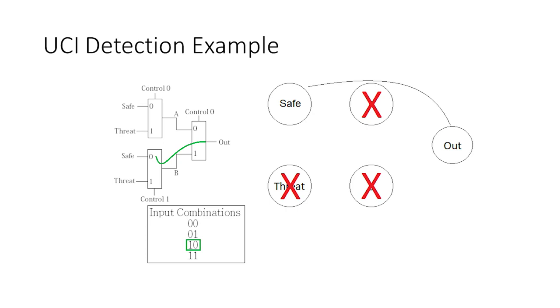So in the end, the Blue Chip algorithm and its use of graph theory has eliminated the threat circuitry, the circuitry handling the value of B, and the circuitry handling the value of A, and has made the determination that through the 3 test cases, only one signal pair is remaining, and that's between safe and out. And so all the circuitry that's described in the top left can be considered malicious, because it doesn't really have an effect on the output given the set of test inputs used during the design, verification, and testing phase.